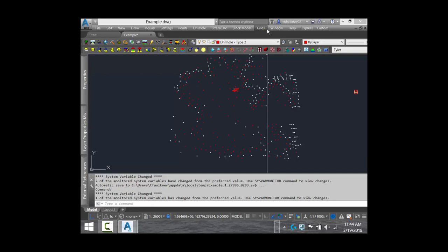Grid files, you can imagine that if we had a surface, we had a mountain, a grid file is kind of like a fishnet. If you were to take a fishnet and drape it over this mountain, anywhere you have crosses on the fishnet where these strings tie together, you would take an elevation at that point.